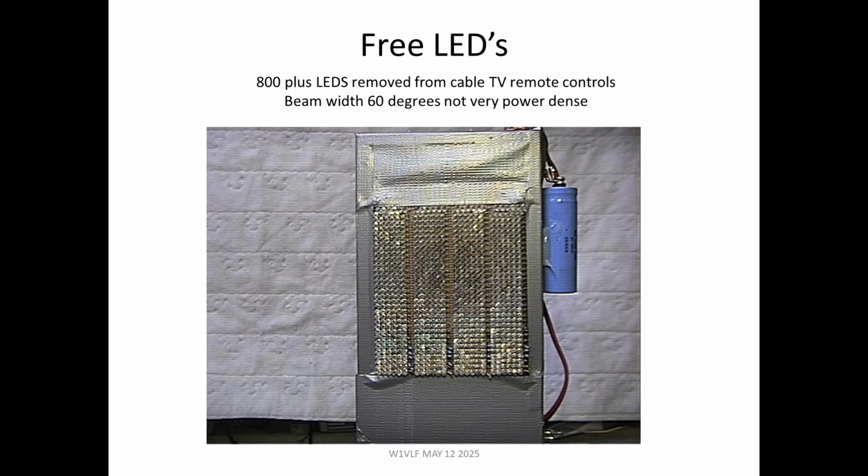Here's the LED array that I built. Each one of these LEDs that you see in this array, I think there's 7: 1, 2, 3, 4, 5, 6, 7. Each string has its own balancing resistor, and then all those series strings are in parallel. You'll see a picture or a schematic diagram later on.